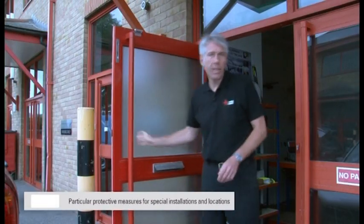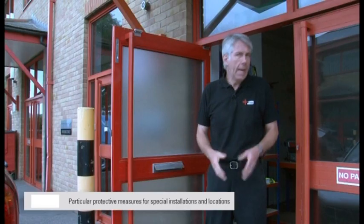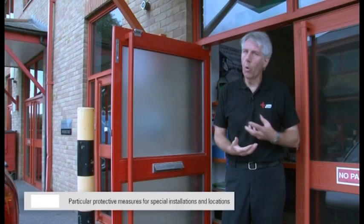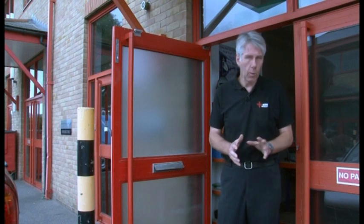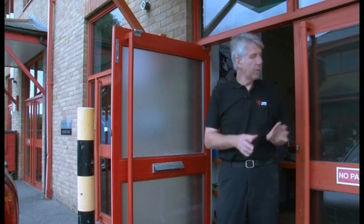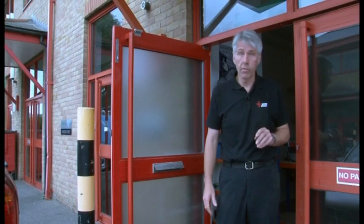Next, we have particular protective measures for special installations and locations. Now, we've mentioned some of these before, but the inspector must carefully examine all of the special locations and installations within the particular premises being inspected and verify that any required protective measures have been adopted. Don't forget that many smaller commercial and industrial premises will not have any special locations or installations whatsoever.